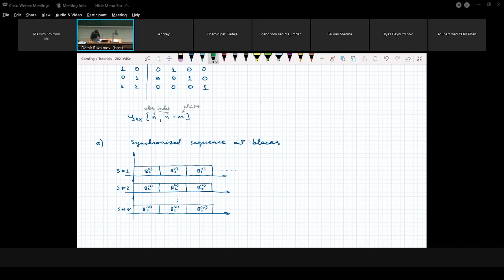It means that you take the first position, the first sample for all sequences, and then you calculate whatever statistics: you average the values over all realizations, you calculate variance, then the square average. You go over all realizations for the first sample of all sequences. This is how you perform averaging.